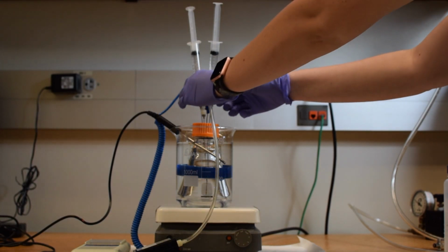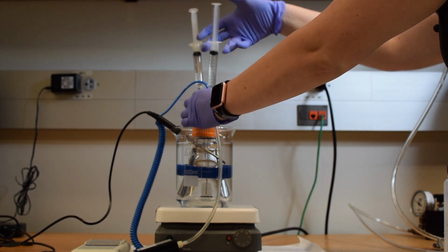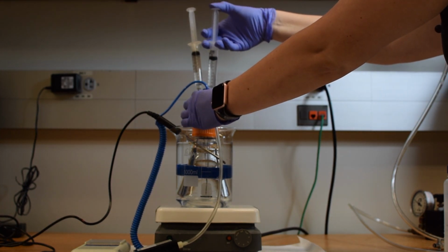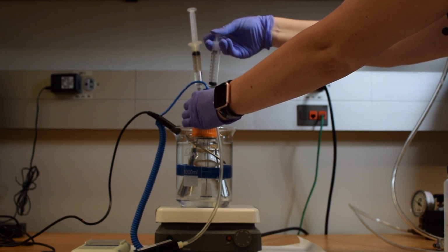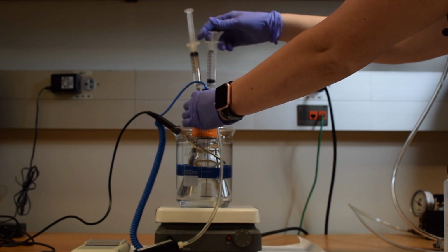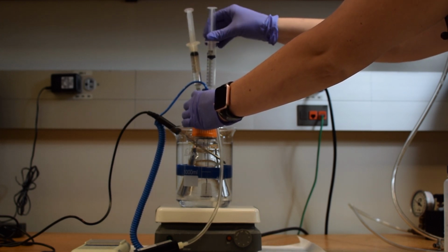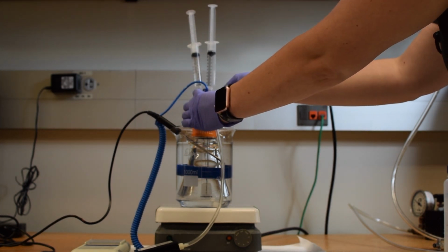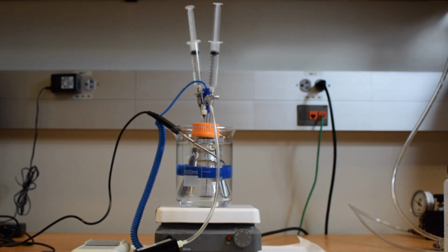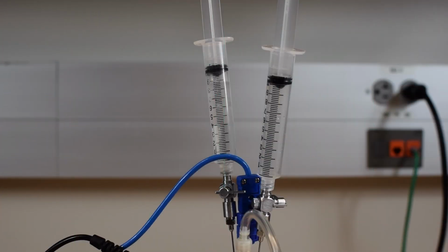Since this experiment is to be an isothermal and isochoric study, an equivalent volume to the volume injected must be removed. Retract the plunger, drawing in primarily nitrogen gas. Be sure to close the connection port valve after injection. Pressure buildup in the system could cause the plunger to be pushed out of the casing. Once the temperature and pressure stabilize, record this value. The increase in system pressure should be equivalent to the vapor pressure of the pure component at the system temperature.